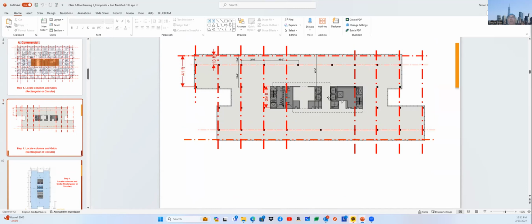This is not ours. Usually the architect discusses it with a vertical transportation analysis specialist. They decide how many elevators they need to serve the building. Obviously, the taller the building, right, the more elevators it needs. Sometimes these elevators can be zoned, and they program it so that some elevators only serve lower floors, some go to the middle, and some only serve the high floors. So I think this is something for vertical transportation.